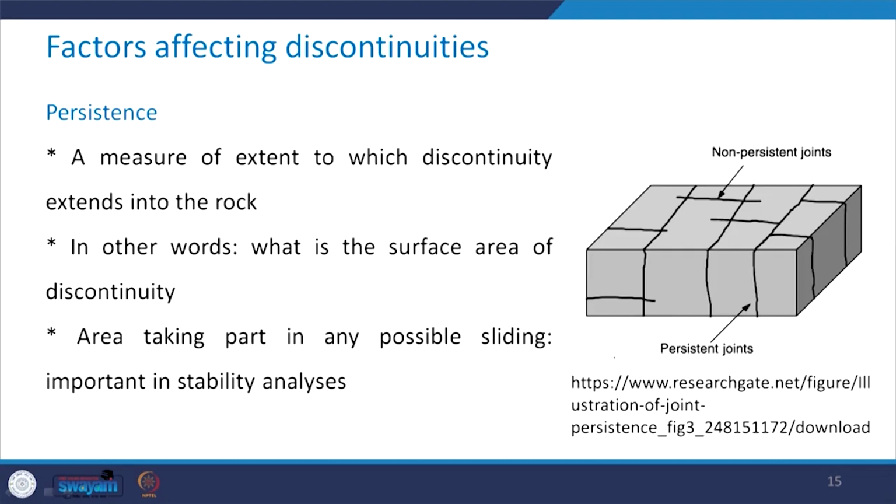Next property or the factor which influences the discontinuities is persistence, a very important one, and it is difficult to measure. So, we have to take some idea in the field. First, understand what exactly persistence is. This is a measure of the extent to which the discontinuity extends into the rock.